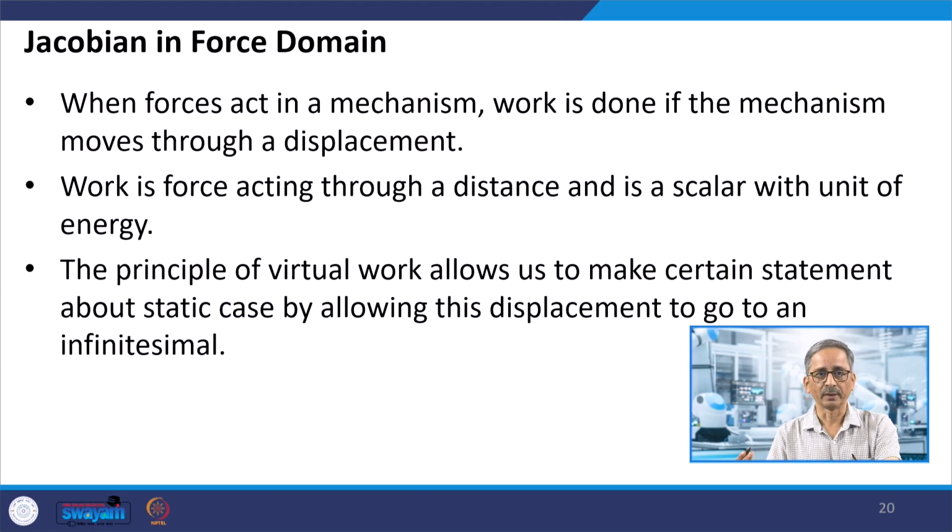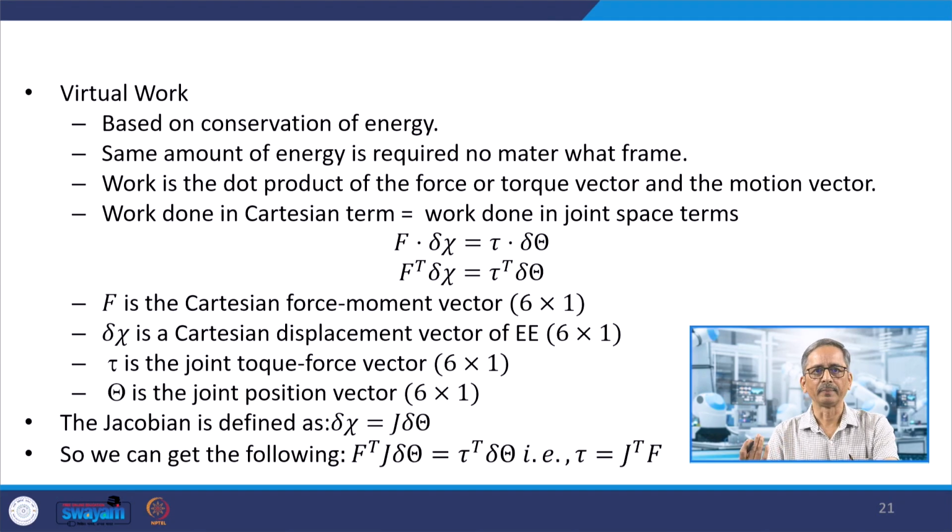virtual work also. When forces act in a mechanism, work is done if the mechanism moves through a displacement, and work is a force acting through a distance and is a scalar, as all of us know. It has the unit of energy. So, we can use the principle of virtual work, where we go for the infinitesimal displacement of the force or moments. The same amount of energy is required no matter what frame you are considering. So, the work done in Cartesian terms is equal to the work done in joint space.